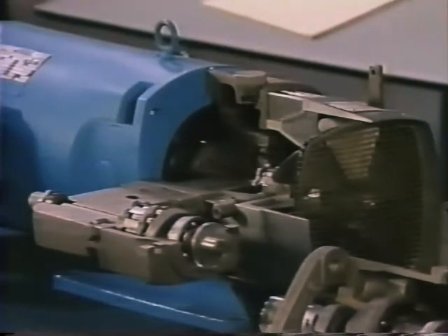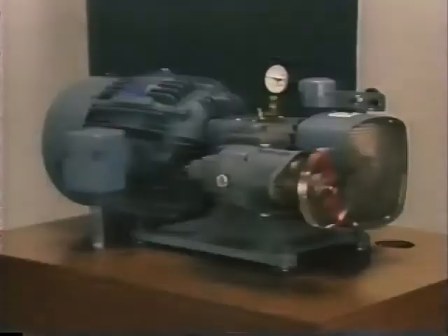Now let's move from our cutaway to a working unit. Right now, the electric motor and pump are turning at 1800 RPM, but there is no movement of the motor shaft. Actually, we couldn't move it if we tried, because the pump yoke is centered, and its pistons can't move in or out of their bores.